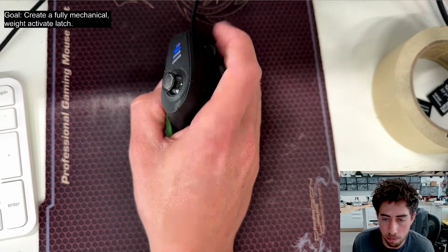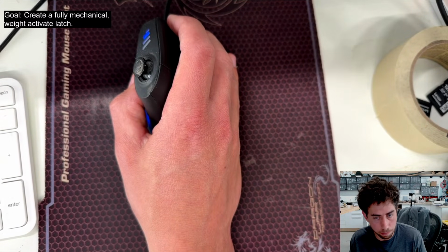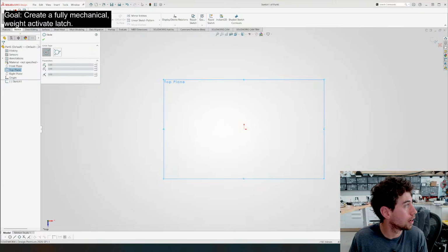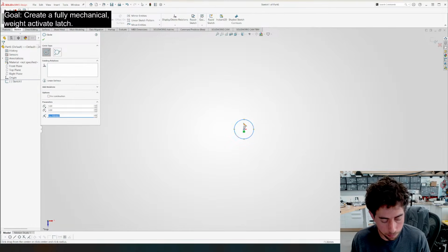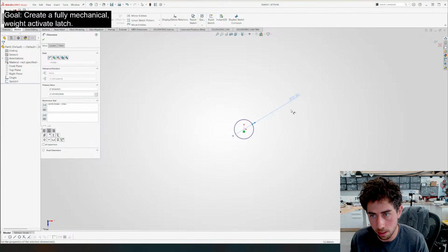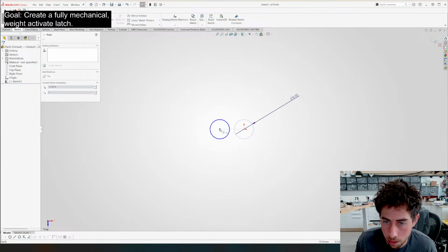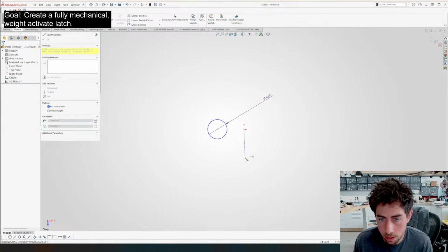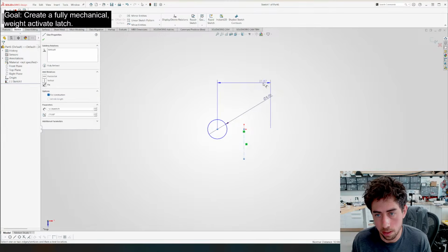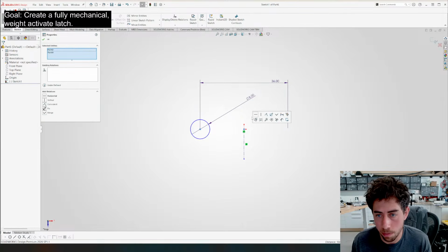I have a better idea. We're just gonna redraw it. Top plane, front plane, top plane. Let me get out of iPhone mode. Boom. We're going to use some 8mm rods and some 8mm sliders. And we're actually going to do 2 of them like this and like this. And we'll make them 36 apart because I just like that number. Boom.